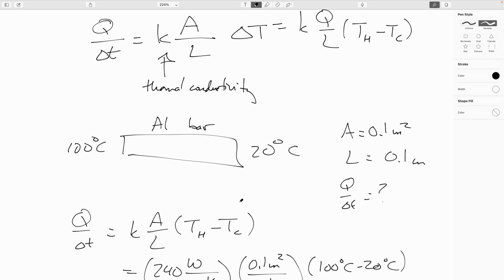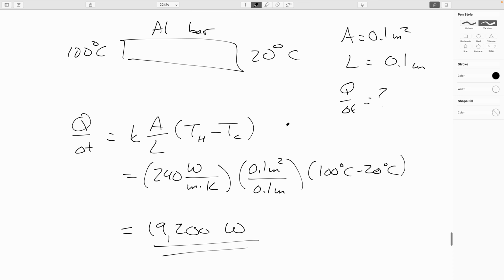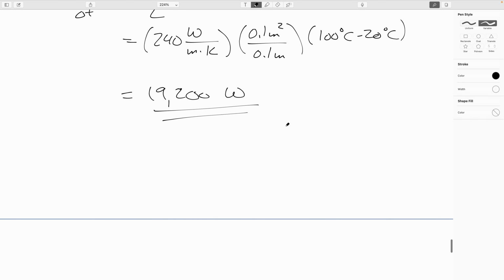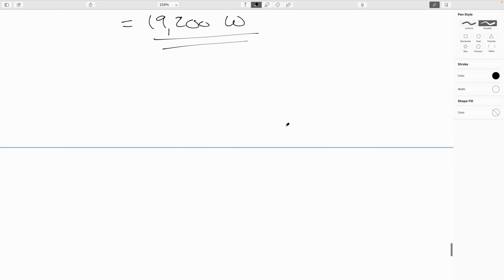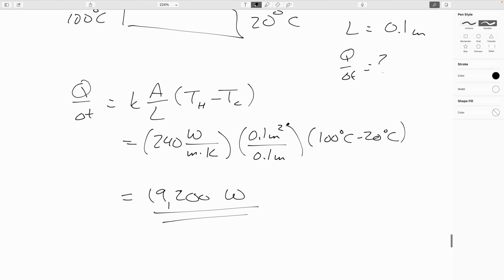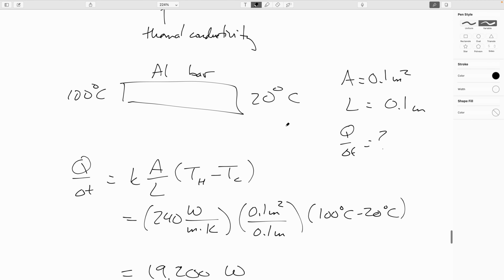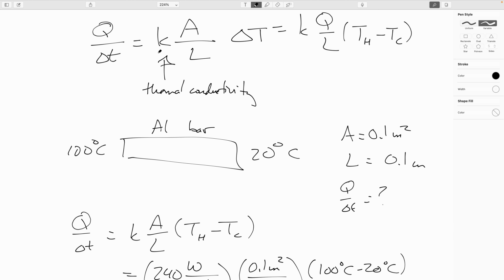Now, just as an aside, a lot of times you'll see thermal conductivities restated as thermal resistivities, which is 1 over that. That turns out to be related to the R factor of insulation. But it's all in British units and it gets really weird. But anyway, big R factors mean low thermal conductivities and also mean thicker, so bigger L bats of insulation.